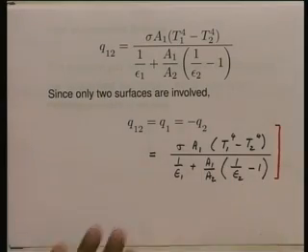So, this expression is also valid for calculating the radiant heat exchange in the annular space between two concentric spheres 1 and 2. Why, for that matter, do the spheres have to be concentric, or why do the two cylindrical tubes have to be concentric? They could even be eccentric, because even when they are eccentric, F1 to 2 is going to be 1 and F2 to 1 is going to be A1 upon A2. You follow? So, even if the two tubes are eccentric or even if the two spheres are eccentric, the relation that we have derived is still valid.